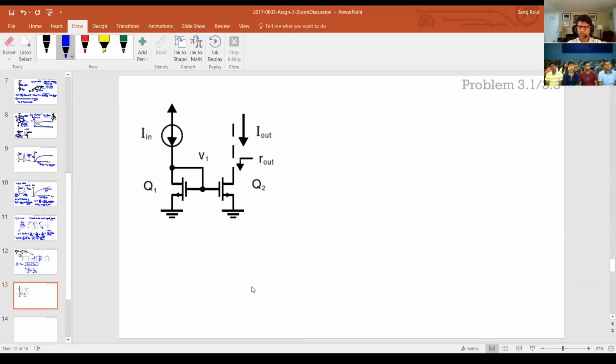So we'll create a VBE1, VBE2, and apply that voltage difference across a resistor, and those two voltages are usually pretty constant, and that will actually generate the current. And once we get that current, we can just mirror it, okay? So for now, you just assume that that pristine source is given to you. When I say pristine source, it's a pretty non-changing source, okay?